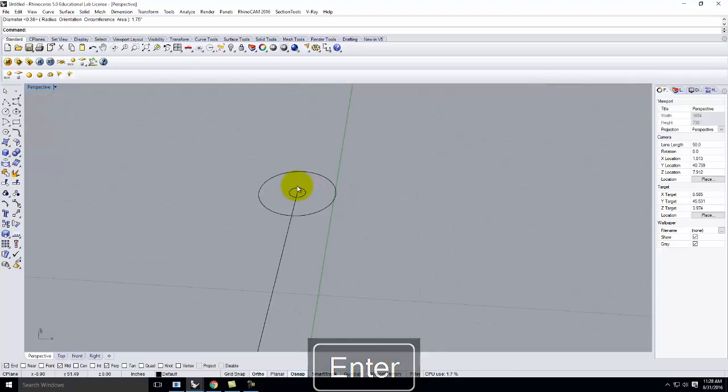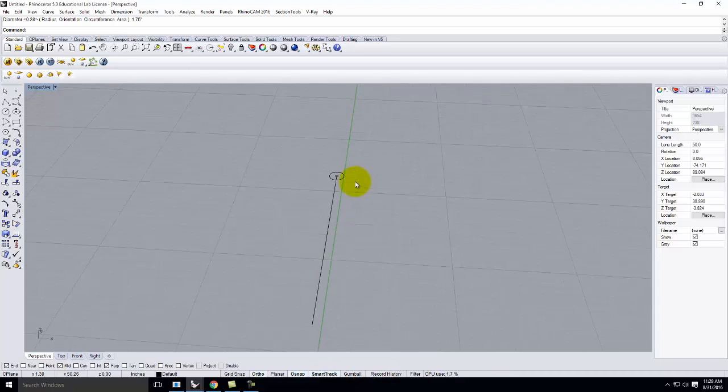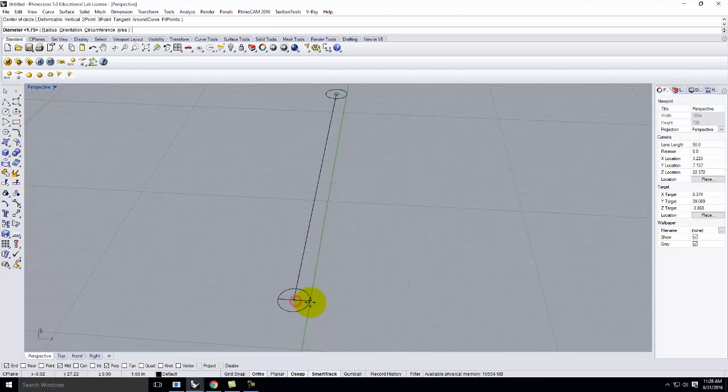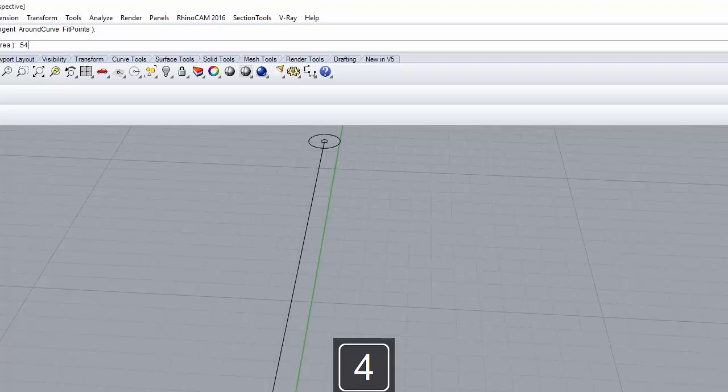Okay? And so I need to do a couple things. I need to create the rod, which is going to be a sweep, and I need to create the little donut at the end. Okay? So the rod's easy. Let me take a line here. This is going to be a 1/2 inch, so I'll do 0.5.